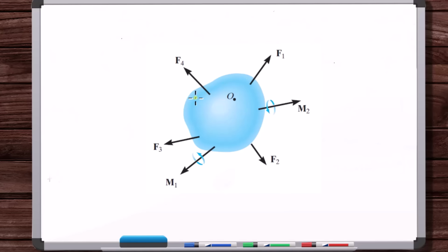So going to the caveman times, if you have a free body diagram with just forces, you could observe and say, I noticed that I can find pairs of forces that are the same magnitude, opposite direction, and separated by distance. And so you could turn that into a couple. And that's what we do here. For the general free body diagram, if there are forces that we can make as couple moments, we'll put them that way. We'll remove this pair of forces here, equal and opposite and separated by distance, and just put the couple moment.